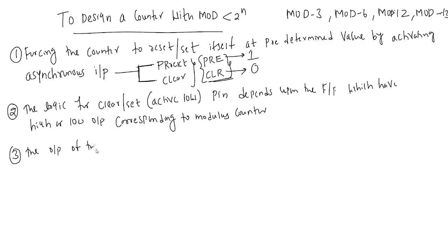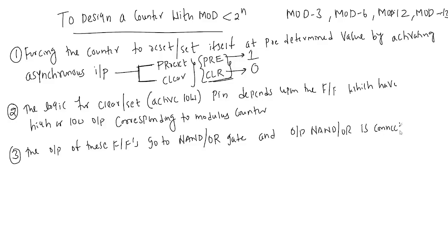The outputs of these flip-flops go to a NAND or OR gate, and the output of the NAND or OR gate is connected to the clear terminal of all flip-flops.